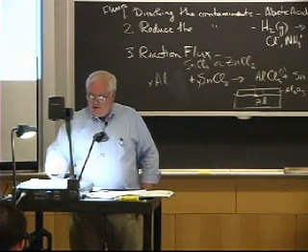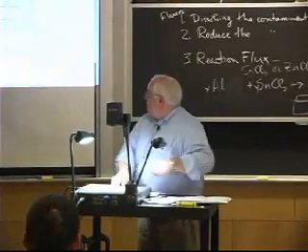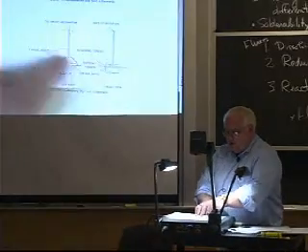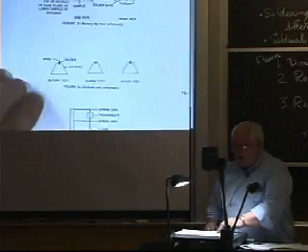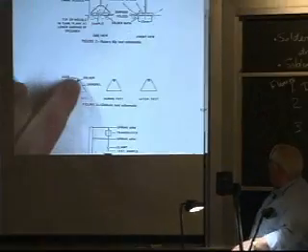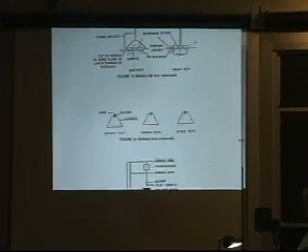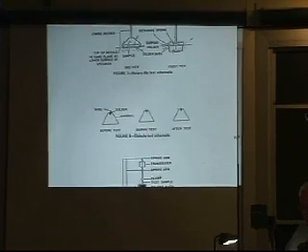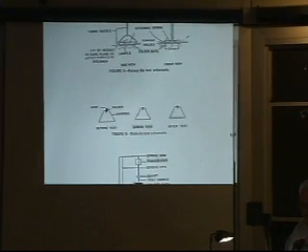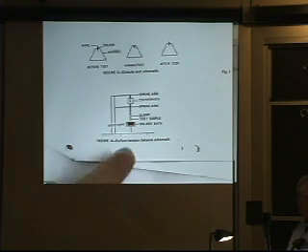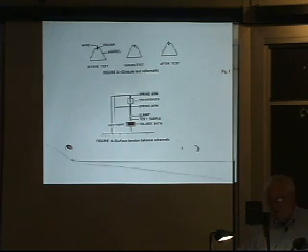Okay, so there's the dip test, just for a simple wire. There's the rotary dip, where you put in a whole circuit board. There's another thing where they basically just take a piece of solder, a wire, and a mandrel, and heat the whole thing up, and afterwards they see if everything flowed together, and you can put flux on there or whatever. And then you get fancy, and for $50,000 you can buy a little tabletop machine that basically is an instrumented solder dip wire test.